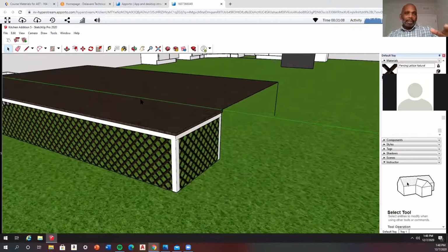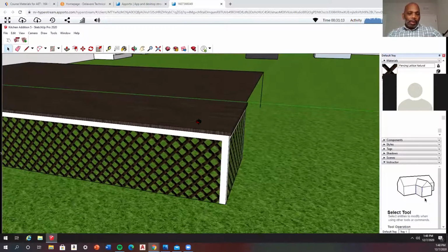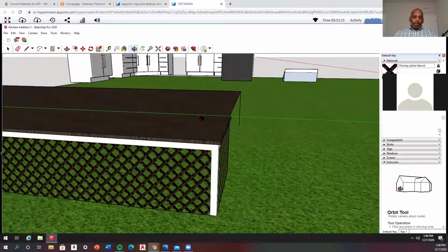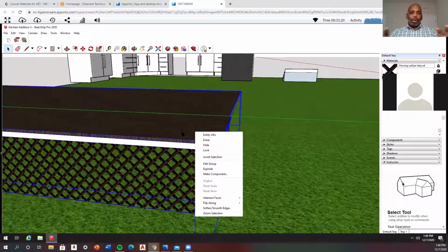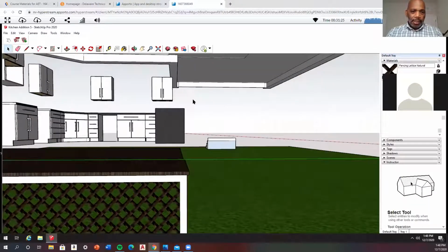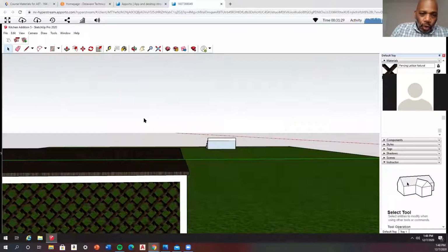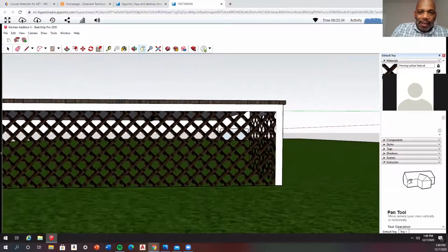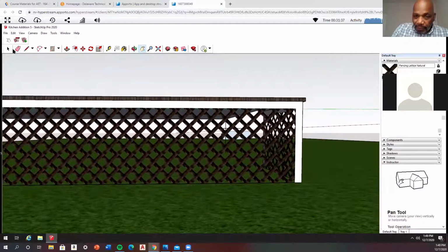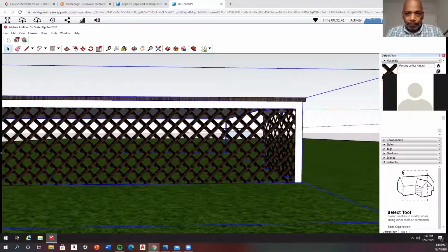This comes down another 12 inches, and it's called a rim board or trim. Just below that thickness, I need a face that's 12 inches deep, not 4 inches deep or whatever you have there. It needs to be 12 inches deep.